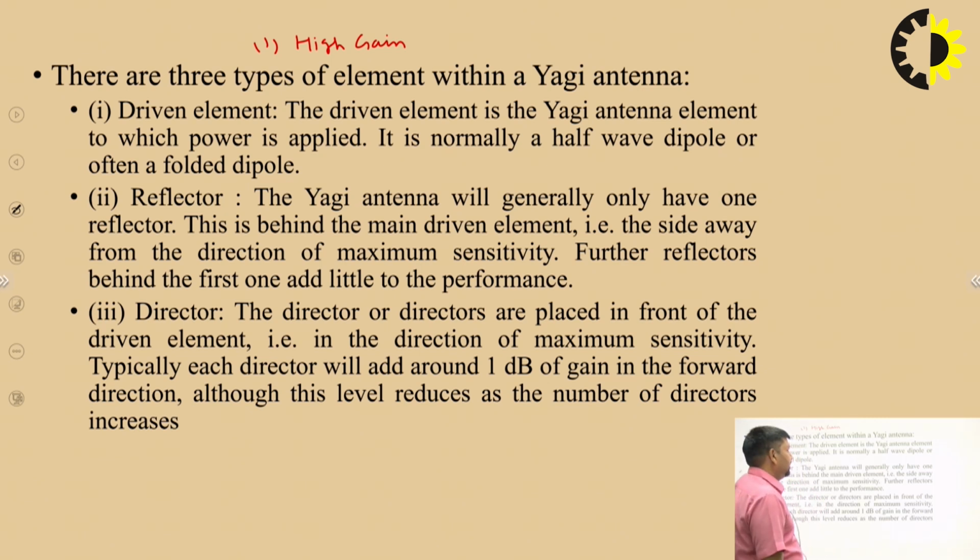The radiation pattern of that antenna is along the antenna array axis, so we also call this type of antenna an end fire array. End fire array properties are high directivity, low half power beamwidth and low BWFN. They provide a high gain of approximately 10 dB to 20 dB.